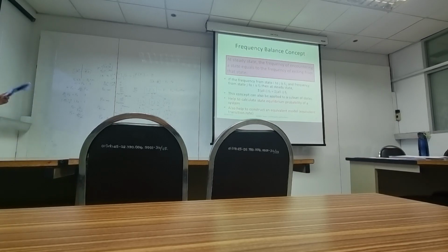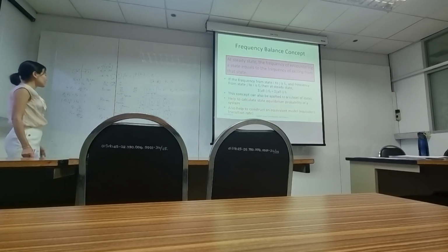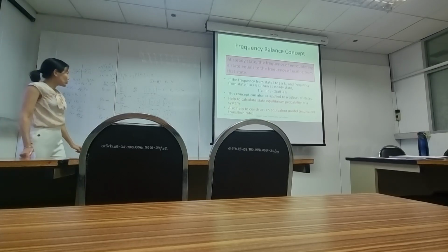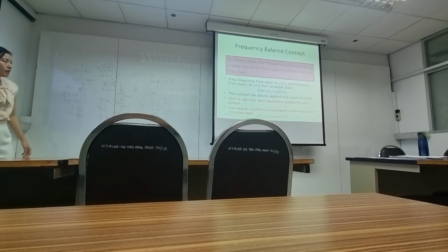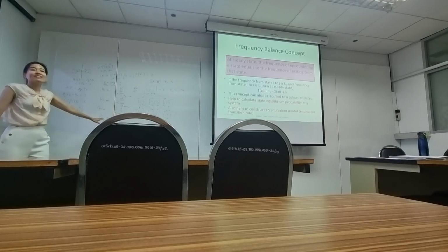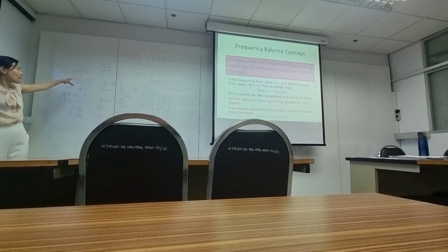Okay? So the frequency balance technique gives you the same thing as the state space approach. But the only thing that we look at in the frequency balance is that we can have this equivalent model of the equivalent failure and repair rates, because you can't have the same idea in the state space approach.